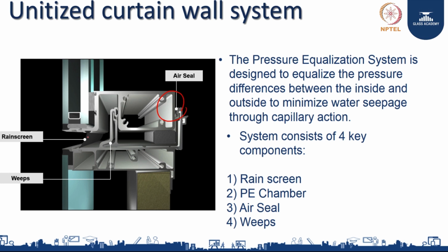Here, yes, you can sometimes have damages or whatever, but if your air seal works right, then the failure can be managed. If your air seal breaks, even if you put a pinhole here, a small hole, they will suck inside. So, be careful when you are attending to a design, whatever form, you must ensure your air seal is in order. So, this stack joint, as I explained, is designed for movement.